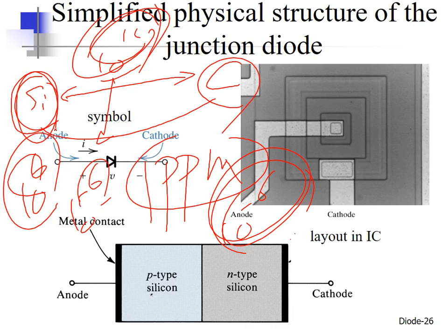But even if you increase the conductivity of silicon lattice by 6 order, compared to a conductor, it's still 6 order less. It's still nothing, I mean for humankind, for daily level. So if you have P-type or N-type semiconductor, you get almost no light, almost zero light, because there is still too much resistance. Never mind for pure semiconductor, I mean intrinsic semiconductor, P-type semiconductor, N-type semiconductor. Usually they are still useless.